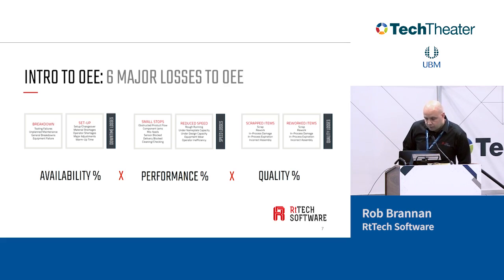Just wanted to start off by introducing people to OEE. I'm not too sure how many people in the room know what OEE is or what it's used for. I'm just going to cover that off now and break it down into the three different buckets that consist of that calculation. So OEE has been around now for a long time, 1950s, 1960s. Started off in the automotive industry, but it has been adapted to any industry now. Essentially, if you're looking to improve the effectiveness of your assets, be it a standalone machine or a production line process, then OEE is a calculation that you can use.